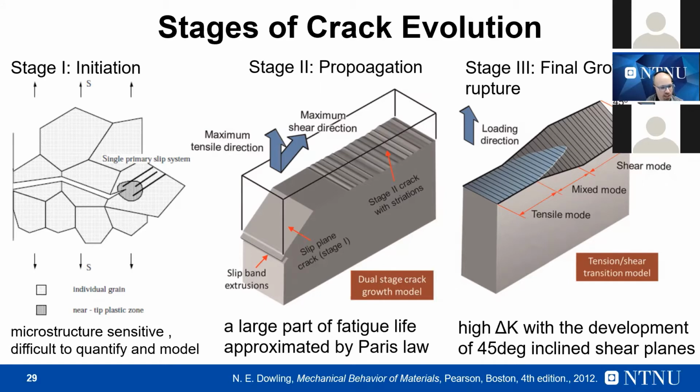But what I want to say is that in the initiation phase, different phenomena occur that are very important and difficult to model. They are due not only to the fact that we have a crack, but also to the material that we are considering: how the material is affecting the crack, for example intrinsic and extrinsic mechanisms provoking this crack initiation, and how the crack is interacting with the size of your grains.